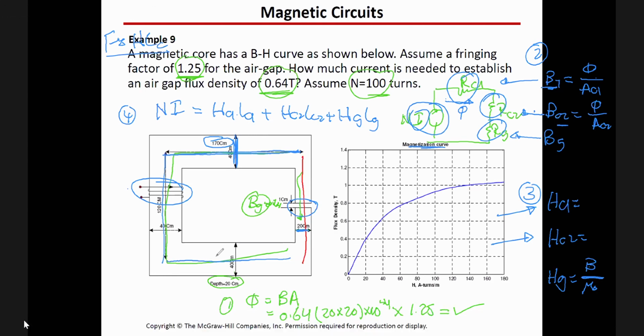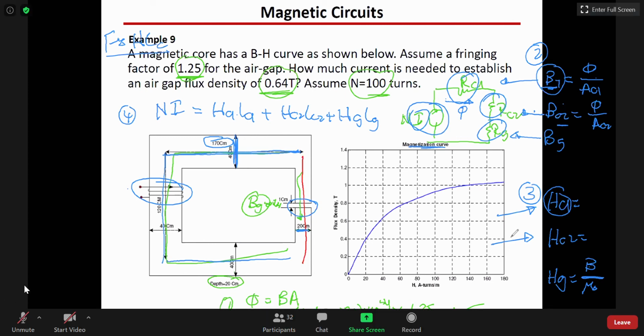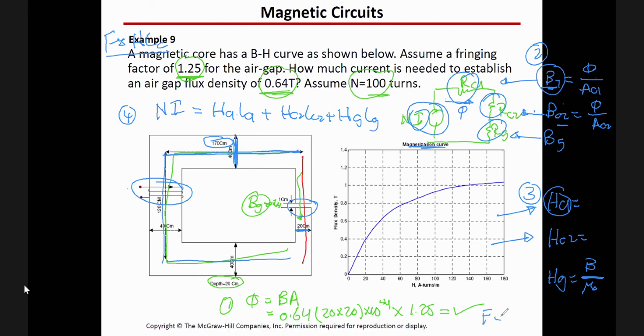Okay. There is another way of thinking. Can I use the reluctance equal L_C over mu A? Then I do the summation of the reluctance. Yeah, you can do this. Once you find this H and you have B, you can find what is mu, equivalent to B1 and H1. And after that, you find the reluctance for that. Then I have to multiply it by the flux to find the total. Yes, similar to what we did before. F is equal to flux times equivalent reluctances.